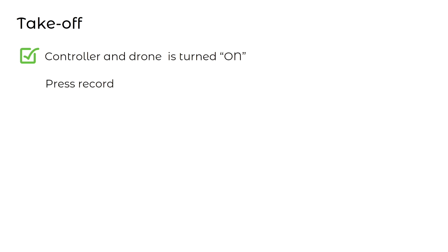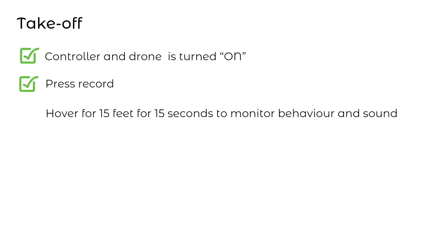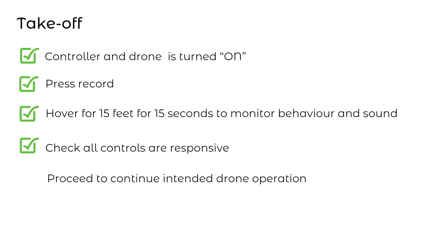Takeoff. Controller and drone is turned on. Press record. Hover for 15 feet for 15 seconds to monitor behavior and sound. Check all controls are responsive. Proceed to continue intended drone operation.